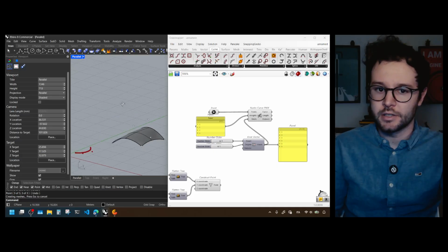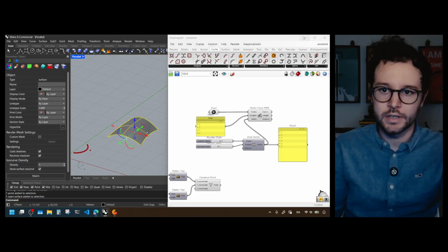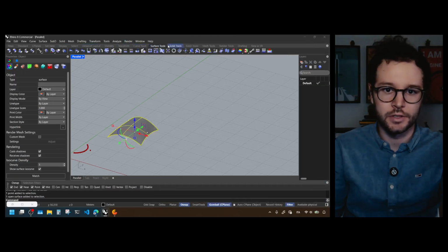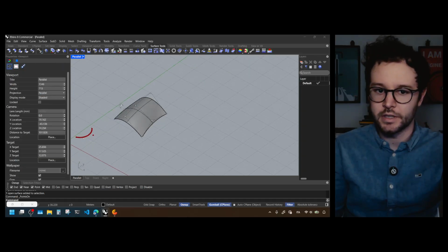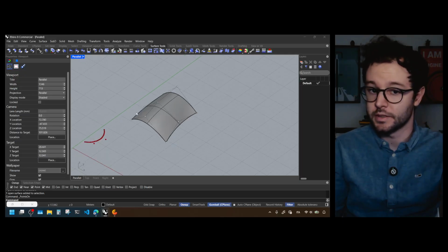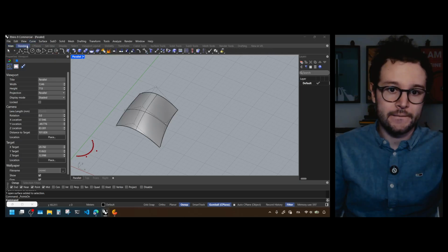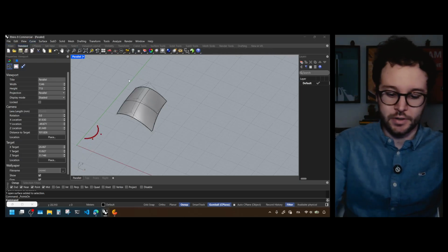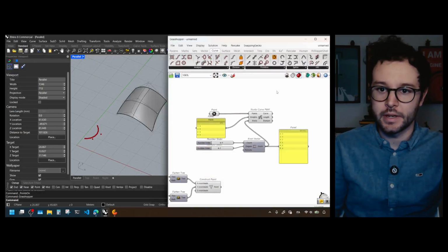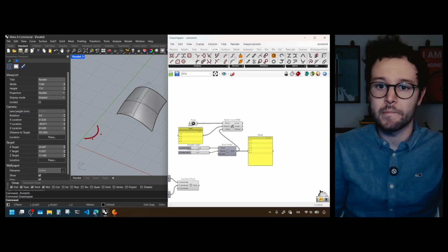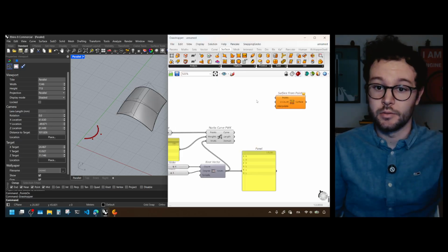And indeed, we get a surface which is controlled by those points. You can also visualize that by going to Surface Tools and turning them on, and you see that you have the same thing that you have in 2D, but now on a surface. Okay, and we can do the same thing in Grasshopper just before we wrap up. There's a similar command: if you go to Surface, Surface from Points, you can take the points.